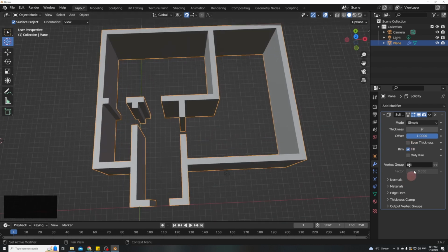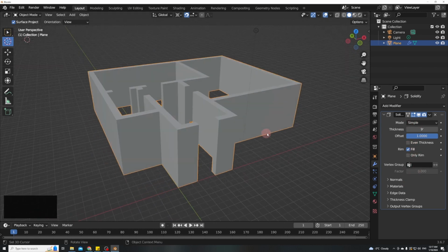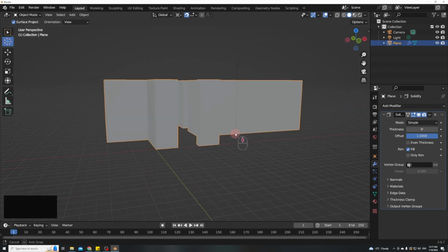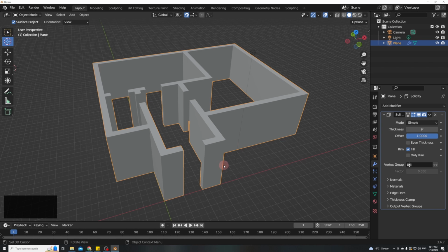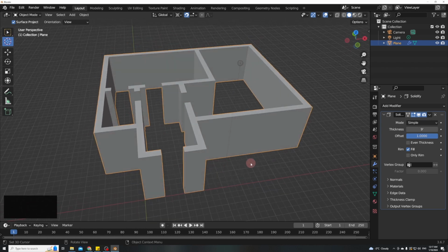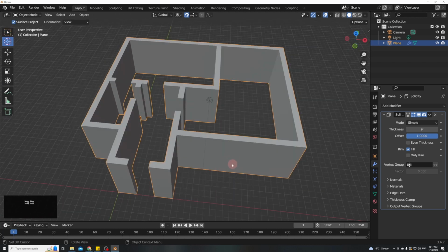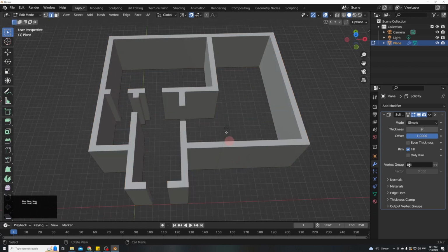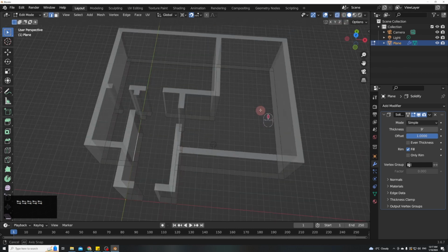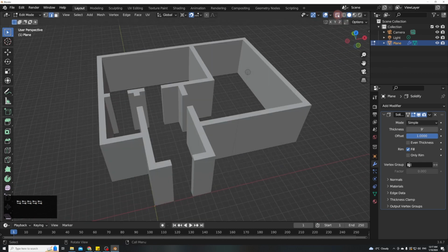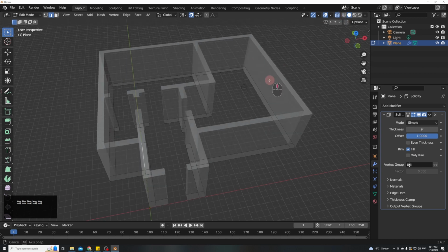You don't have to worry about any of the other settings for this. It should automatically go up perfectly in all directions. But if it doesn't, that might be a sign that there's something else wrong with what you did. And you might have to go into your mesh and tweak it. If you want to edit your mesh and you press tab and you notice that it's not showing up, well, it's because you might need to turn your X-ray mode on.